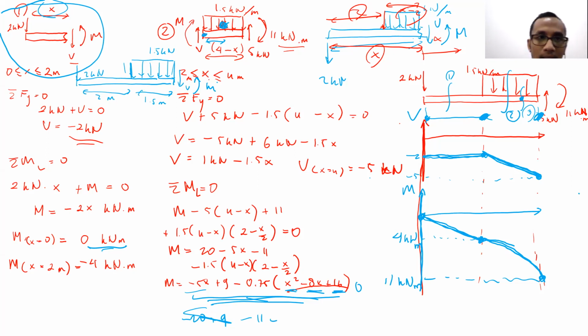Yes, sir. Then after you draw the final free body diagram like that, you can simplify. The centroid is here, so this is the representative of the concentrated force. The location is 0.75 meters from the right cut, or 2.75 meters from the left edge. Do you get it? Yes, sir, I get it. Thank you, sir.